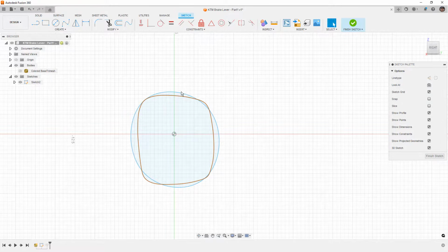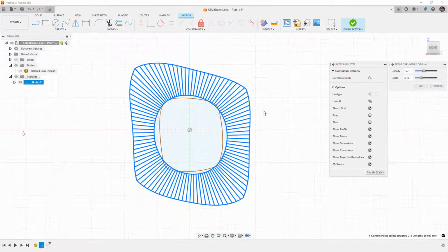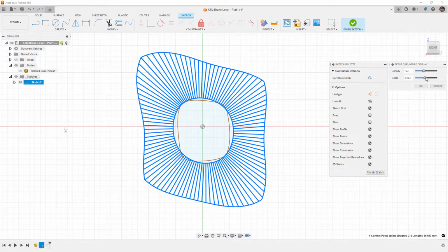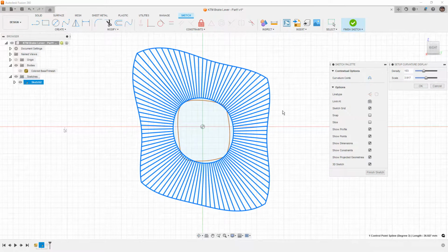Let's go ahead and take a look at the differences between these two. So again, plus or minus 1, that actually looks pretty good. It looks better than it did on the remeshed version of the scan. It still has these spikes in the corners. Those happen exactly where the fillets are, or where the fillets would be if this was a prismatic part, but everything else is relatively smooth.